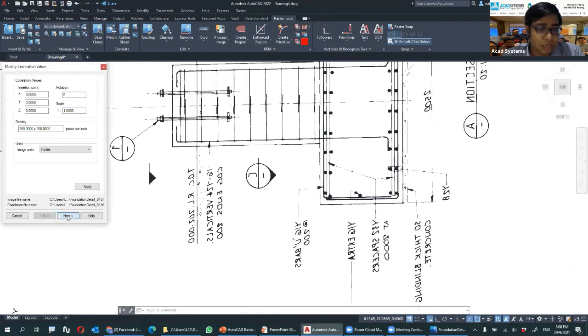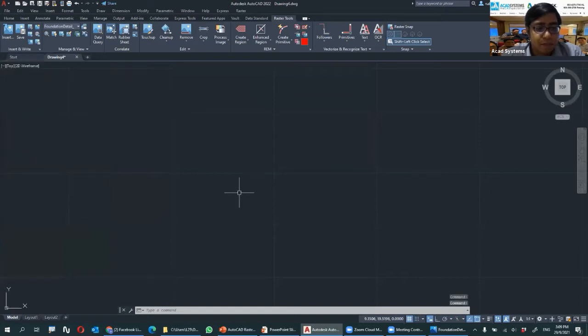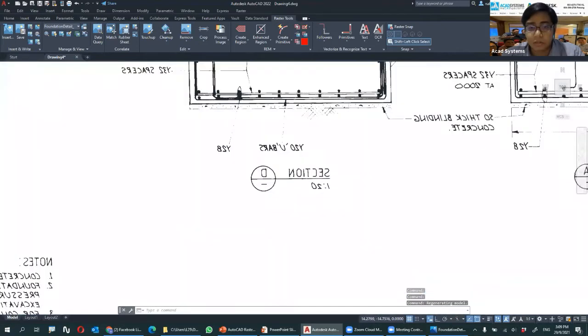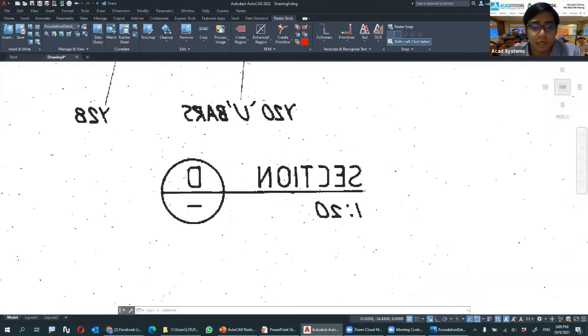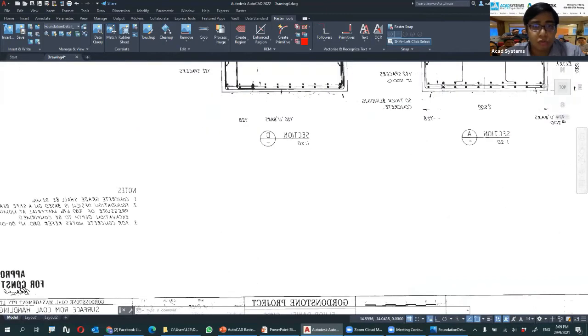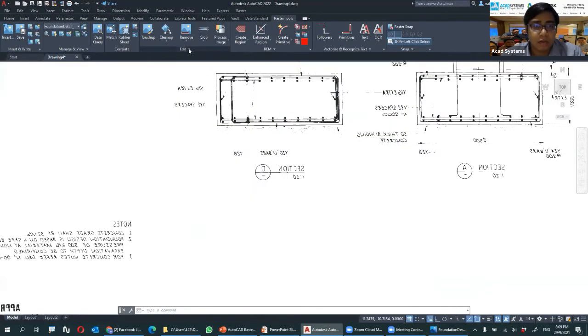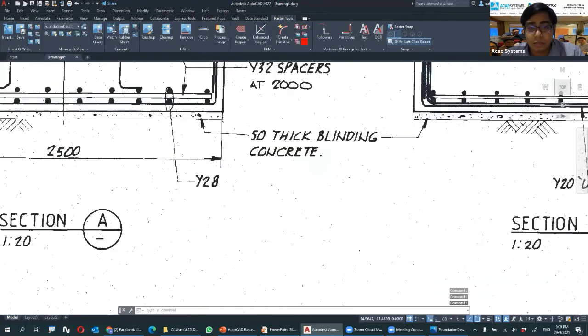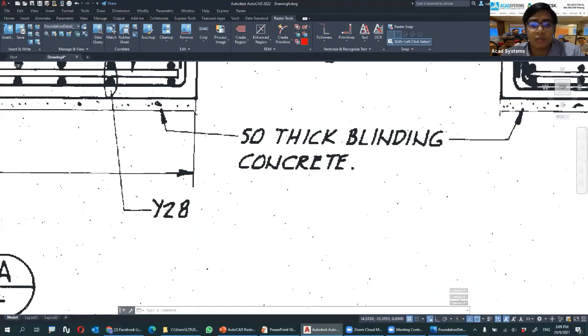So I'm going to go ahead next, and I'm going to correct the rotation. Let's go with -19. I'm happy with the scales. I'm going to click finish, and it should appear over here. But you can see it's not actually mirrored correctly. To edit that, you can go to the edit over here, and select from the cleanup the mirror. Here I can rotate, so it is oriented or mirrored correctly.